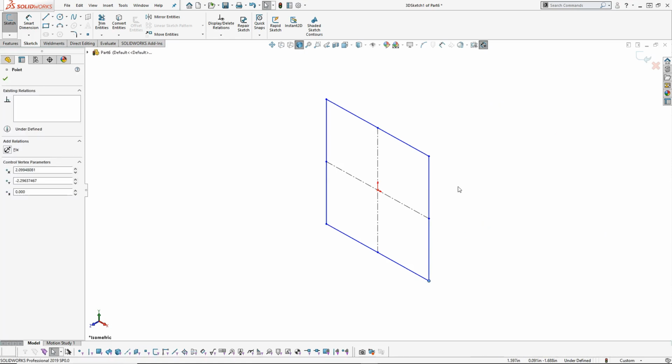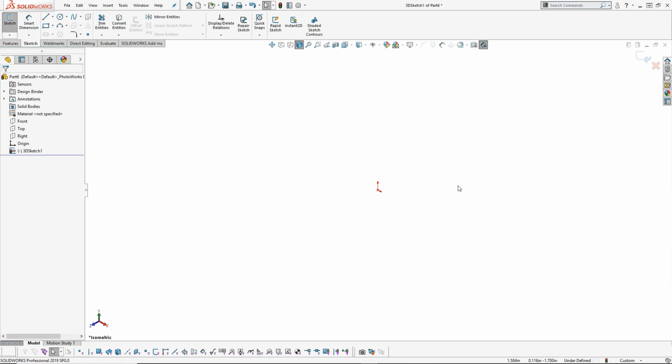Most of the relations are going to be the same or similar, but there are a handful of specialty items for the 3D sketch specifically. One of the things that we can do is decide: do I want my enclosure to be centered about the origin? Is that going to be helpful? Maybe the leading edge? I think that most of the time I've found that having it at the midpoint kind of helps visualize the symmetry or the geometry. So maybe the front mid or the center or the back mid as an option.